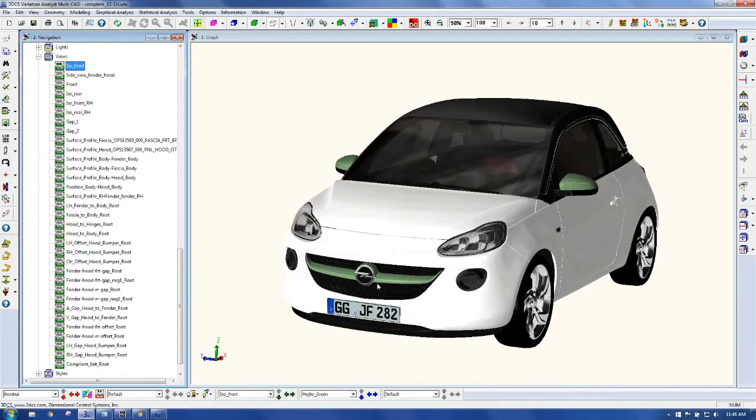So with KeyShot, two of the biggest things I would say to keep in mind is making sure that when you import your geometry, you're importing it using the original coordinate set. That's called keeping the original within KeyShot. And knowing how the materials are going to work and how they're going to be tied to a part name and not an actual material name. Once you're in KeyShot, we can change all that so it's organized a little bit better. But upon import, that just needs to be noted.